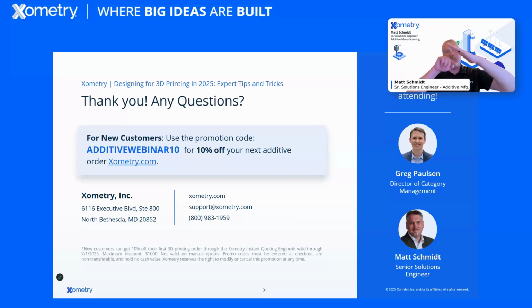It'll be an acute angle. It might need some support, but in this case, you are taking less volume per slice. You've got less heat per slice, and you will get a much better result. If you have to, stand it straight up and ask us for advice on how we can help you with orientation to create a better part.